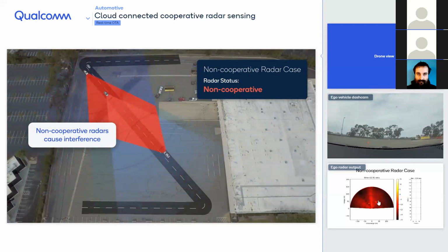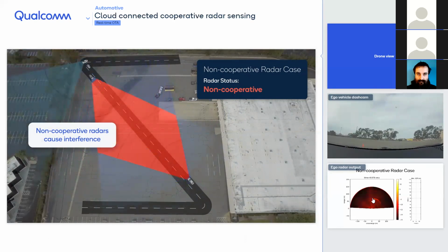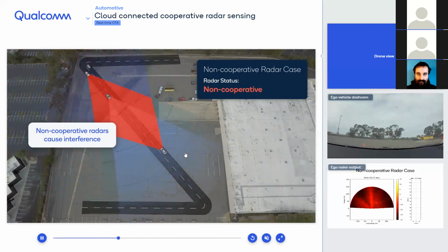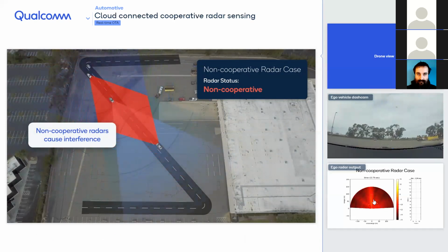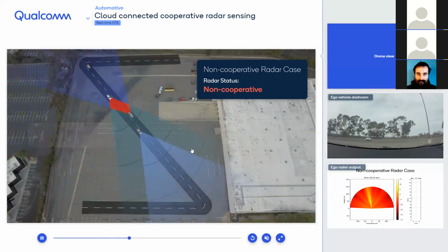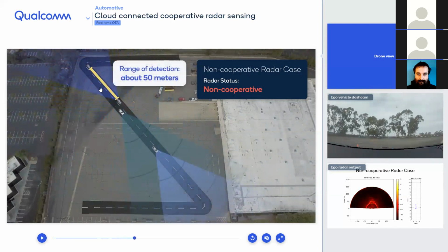So you can tell that there's some interference approaching you. Let's go back for a while. By the fact that there's some circle here that keeps approaching you. But once that circle is close enough, something else happens. You see the screen is bright all over the place, and then you cannot detect anything at all until the interference passes. Then you can see this target at around 50 meters away. In some cases, this reduces the time that the radar system gives to the driver to react to a possible crash scenario.